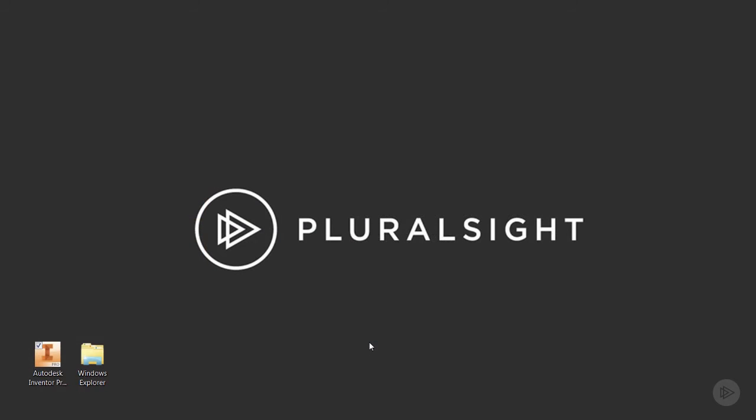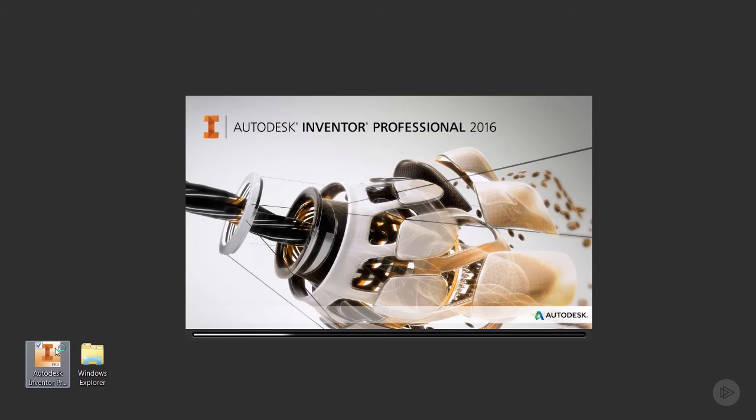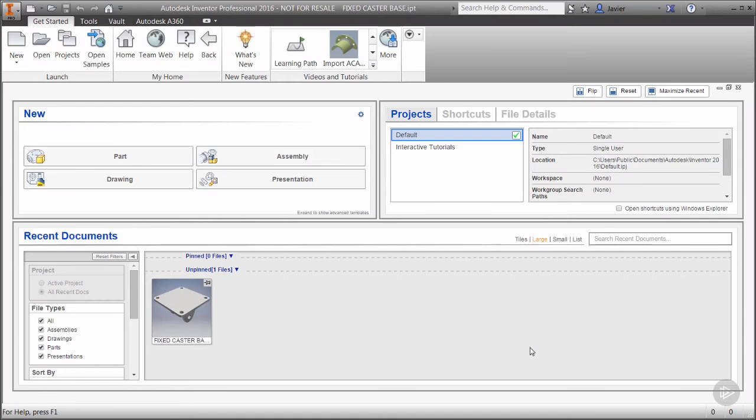If you haven't already done so, go ahead and launch Inventor now. Let's make sure that we're set to the default project inside of Inventor. Now, a project file is a system for organizing and accessing all files that are associated with a particular design job. When you install Inventor, it installs a default project automatically. To set or edit a project file, you want to make sure that all your Inventor files are closed first. Otherwise, Inventor will simply not allow you to proceed.